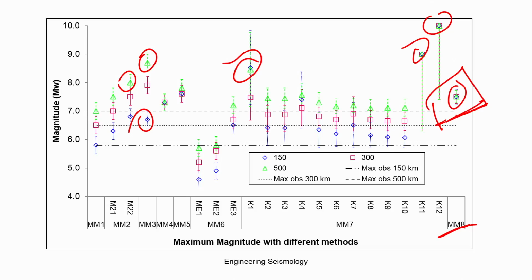If you want to consider the entire seismic study area as a single region, or you can also get an individual fault length based Mmax, which is also possible. That also does not change irrespective. But with other approaches, when you change the seismic study area, your Mmax value keeps changing. That is not the issue with the newly proposed method.